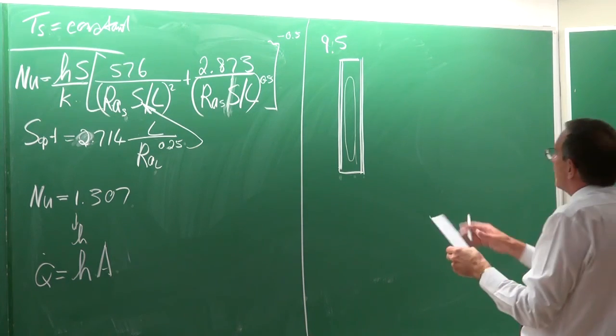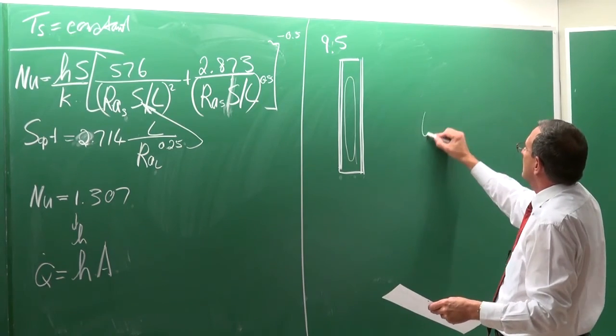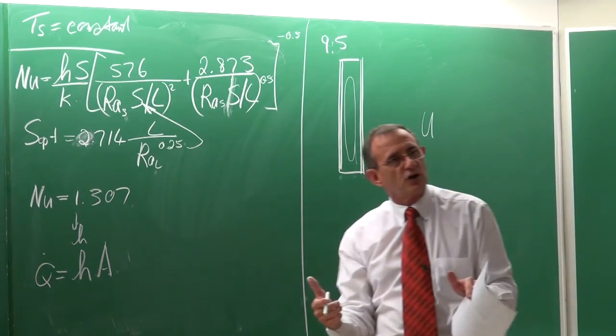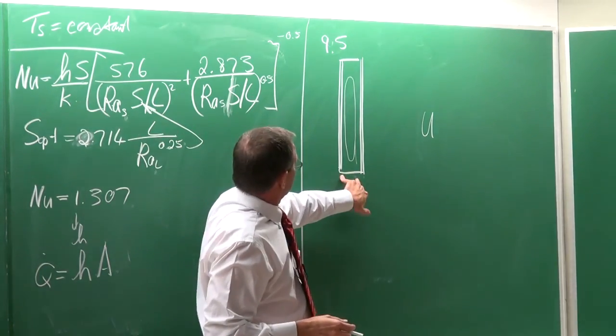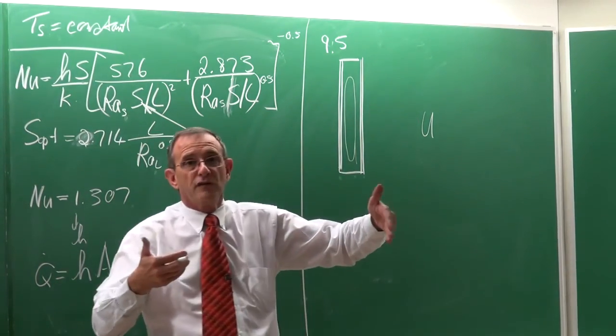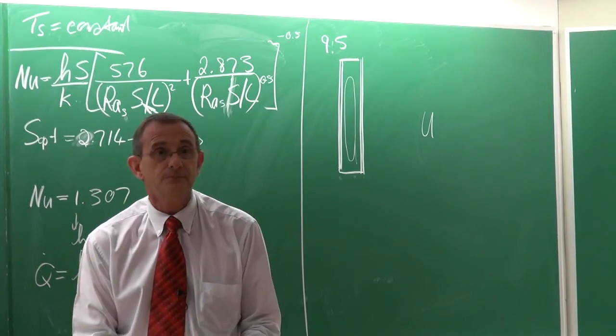But this, if you go through it, reduces to, at the end, something where they get the overall heat transfer coefficient, okay, the U. And many of you that have worked, maybe that did some holiday work in the air conditioning and ventilation industry, would have seen that you use your designs with a U factor. Okay. Now what is interesting with that is, of course, for glass, you would like this, obviously the heat transfer coefficient, to get it as low as possible for the natural convection. How can you do that?